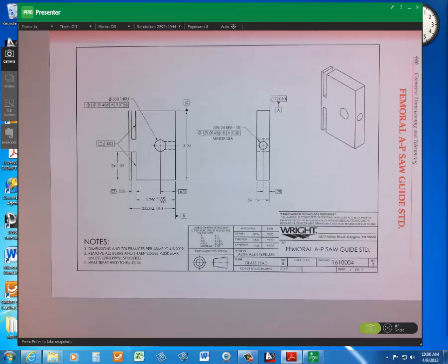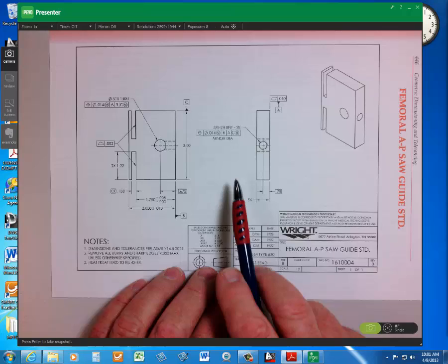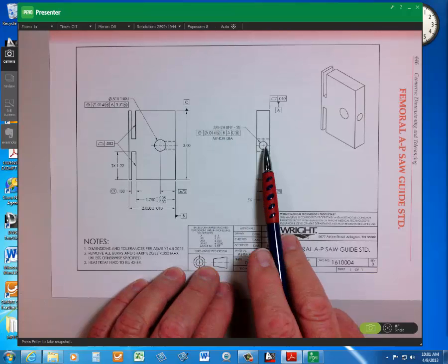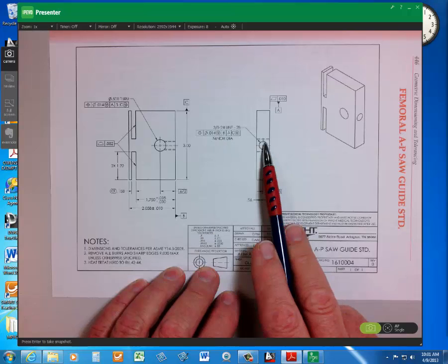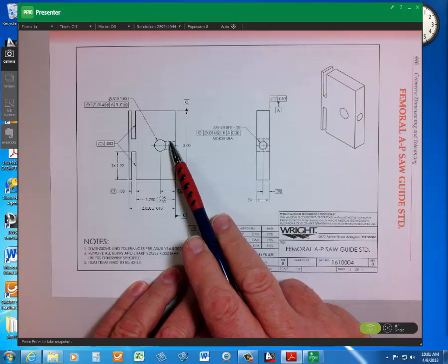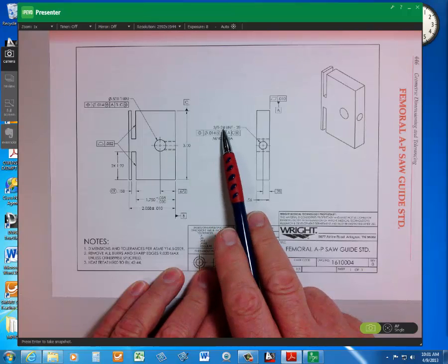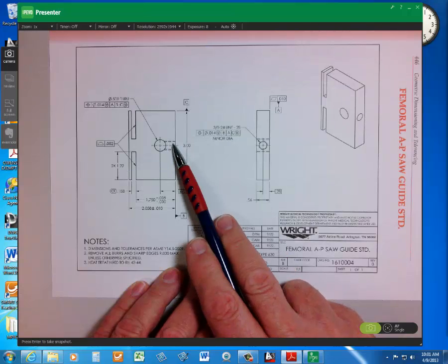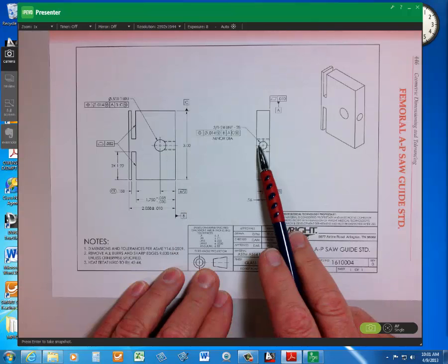Okay. Next is the 3/8-24. Now this is a threaded hole, so it's 3/8 major diameter. That's the hidden line you're seeing there, and the outside hidden line you're seeing here. 3/8 diameter, 24 threads per inch, which we don't show. We don't actually draw the little sharp V threads. We just represent it with hidden line.